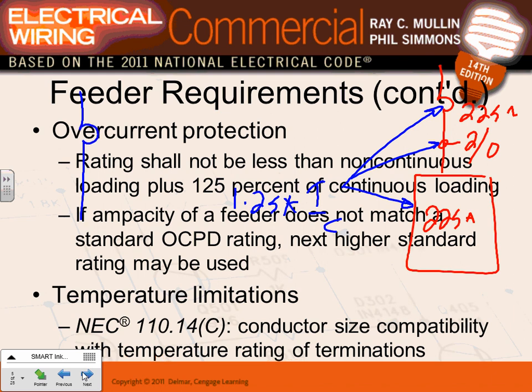Let me take this. This is a 100 amp panel, and the feeder is number 1. I want somebody to tell me how much continuous load can I get out of this 100 amp? The load is the opposite, 80%. You're on the right track. So my load here is only 80% of the overcurrent protection device. What's 80% of 100? 80 amps.